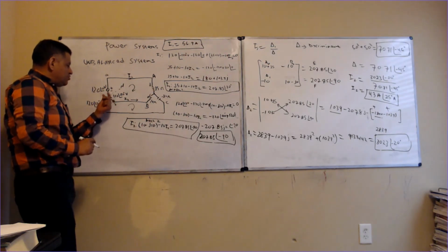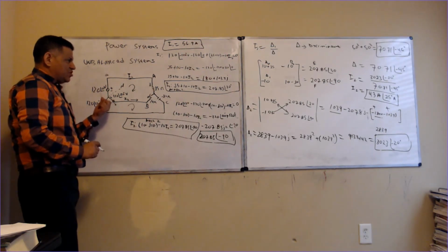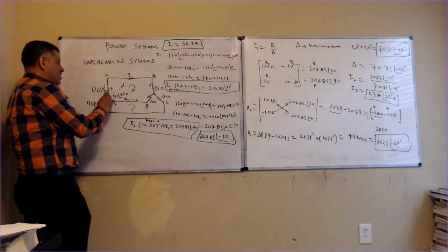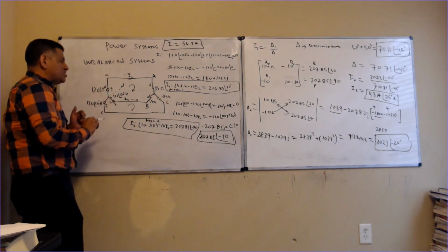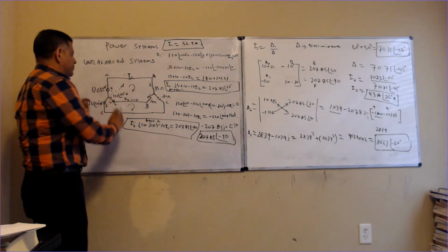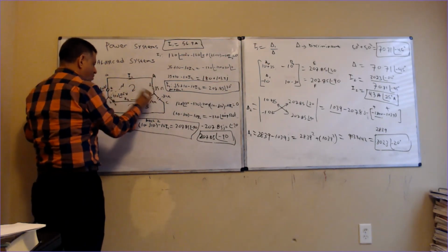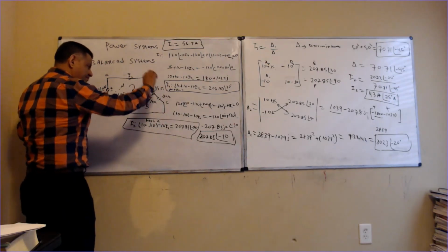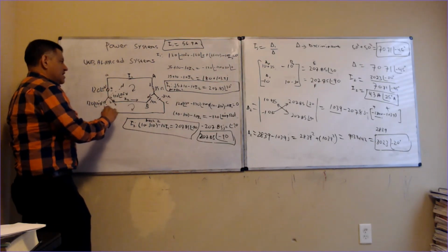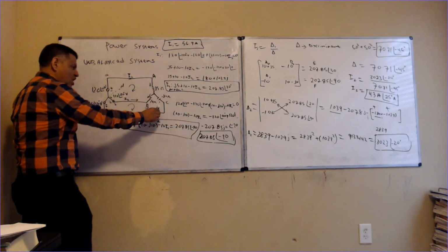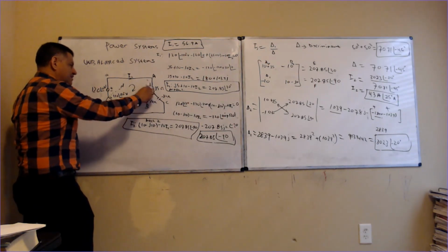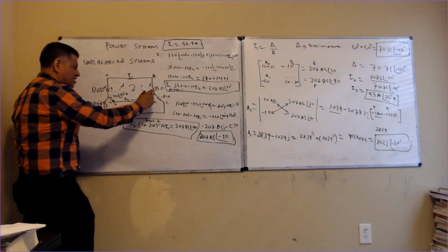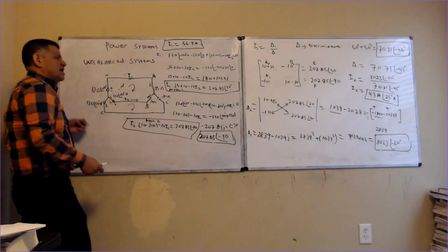This is trying to balance it out, to make it equal zero, because that's what Kirchhoff's law tells us. But the bottom line is this is not one node. This is like three different branch circuits coming out of this. We can prove that if you go back here, it's one; this source is another one, and this source is another one. So it's like three different branch circuits in one system. When the loads are different in these lines, it creates an imbalanced load, and that's when we start having problems.